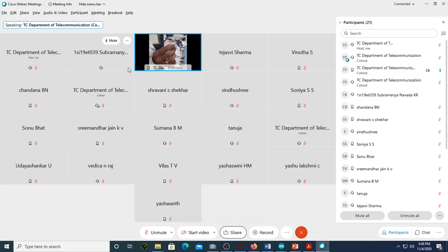So we have a multimeter. Now we are trying to see the continuity of this. So this is 1A, maybe 2A. Now it is open. When I press it, just listen to that sound. Are you getting the sound?